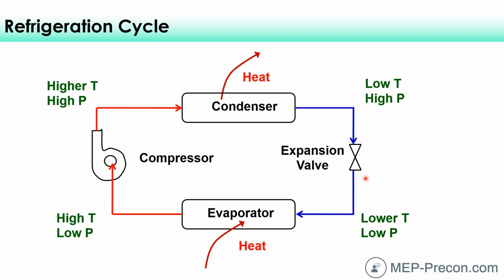Trouble is, that's not going to last very long, because once all the molecules are out of your aerosol cans, well, that's the end of your refrigeration cycle. So all of this is in a closed system. The refrigerant is not going to leak, hopefully, as long as there are no leaks within all the joints. And that compressor drives that refrigerant to do what it does within each of these components. Each one of these things does a different job to that refrigerant, but it's all for the purpose of removing the heat out of the air within that evaporator. Whew, that was a lot. So hopefully you understand that.